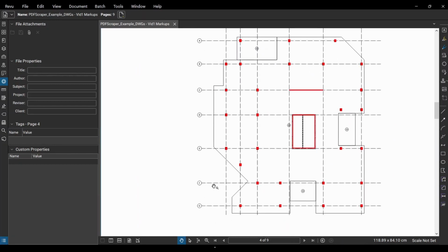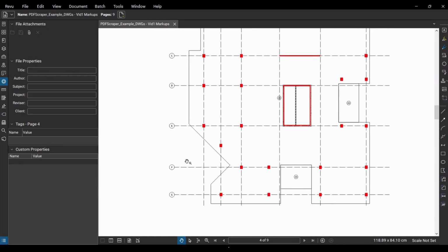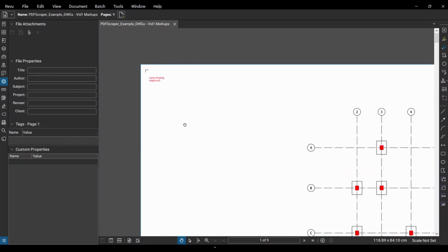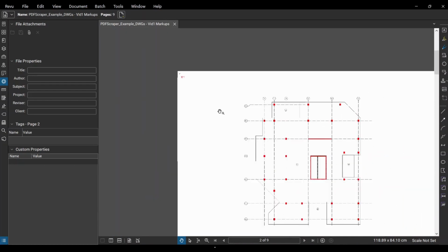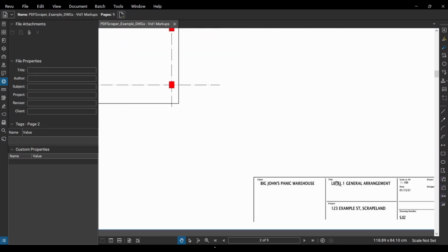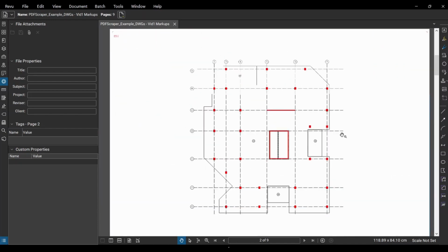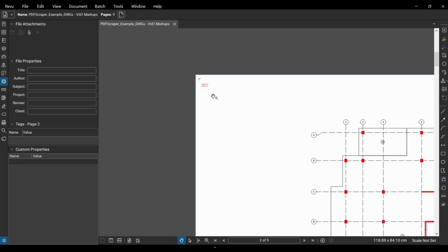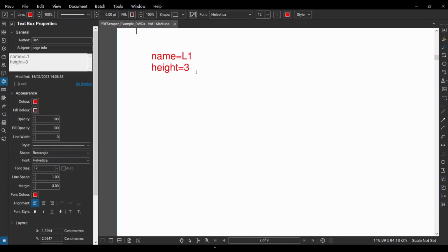So there's one last thing that I'm just going to run through, and that is going to be the alignment that I mentioned before. But before I do that, often you'll get a level or a PDF page that actually represents multiple levels. So this might be level 1 to 3. In which case we can just set a repeat on this page. So all I would do is, on this level, add another line and just say repeat equals 3, and it'll repeat this level 3 times and automatically increment this name. In this case, we've only got 1 level per page, so I don't want to repeat.